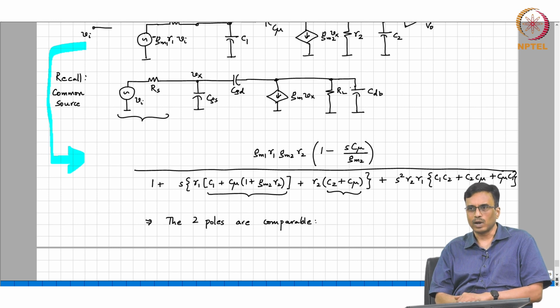So, the quality factor of the closed loop poles. If we just use the op amp as is, the closed loop system might technically be stable, right? But in reality, the quality factor of the closed loop poles is the square root of A naught square F, which is A naught root F, and A naught in this case is gm1 r1 times gm2 r2.